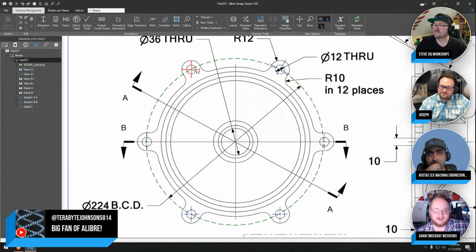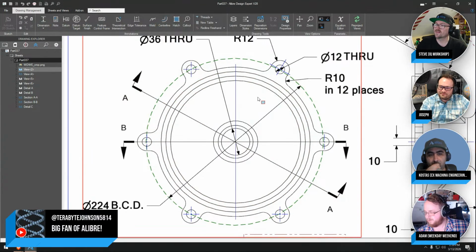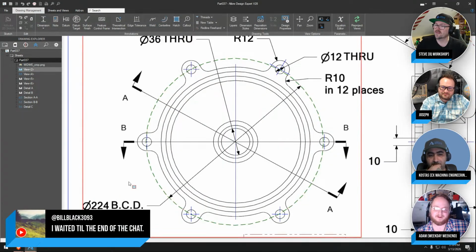Right now they look like this. How do I make them run perpendicular to my bolt diameter here? How do I properly call these holes out? You use a circular pattern is the unfortunate answer. I believe I did circular pattern these.